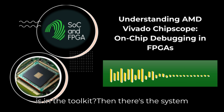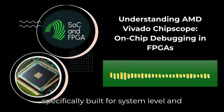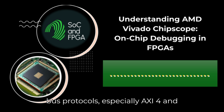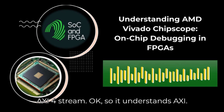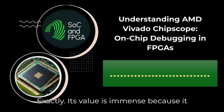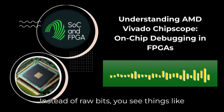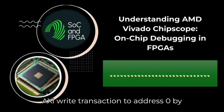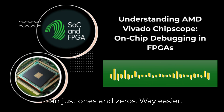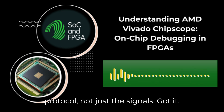Nice. What else is in the toolkit? Then there's the system ILA. Think of it as an enhanced ILA, specifically built for system-level and protocol-aware debugging. Its big advantage is native awareness of common bus protocols, especially AXI4 and AXI4-Stream. Okay, so it understands AXI. Exactly. Its value is immense because it automatically groups and presents bus signals at a higher level of abstraction. Instead of raw bits, you see things like AXI write transaction to address 0x40000000. That's much easier to understand than just ones and zeros. Way easier. Invaluable for debugging complex interconnects. You're debugging the protocol, not just the signals.